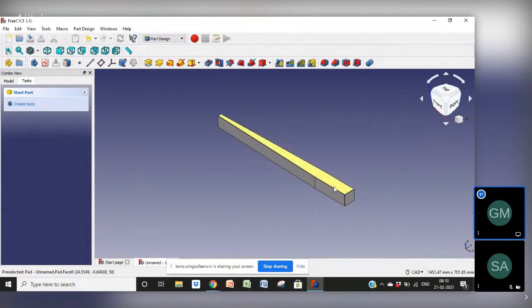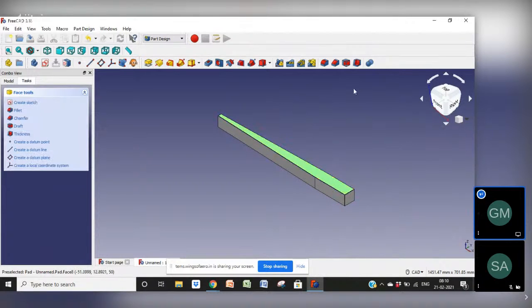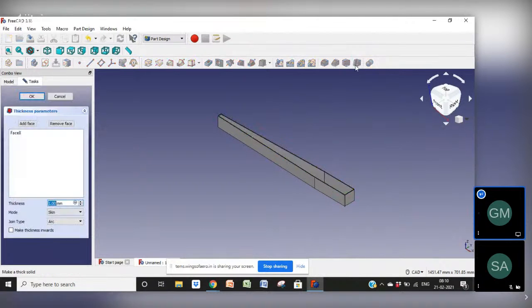Here I will do one thing, make it hollow. Here, this is the section view. Skin thickness would be inside. Okay, and let it be 2 mm thickness. I think I chose this one, yeah, it was 3 mm while making that original aircraft which I made.